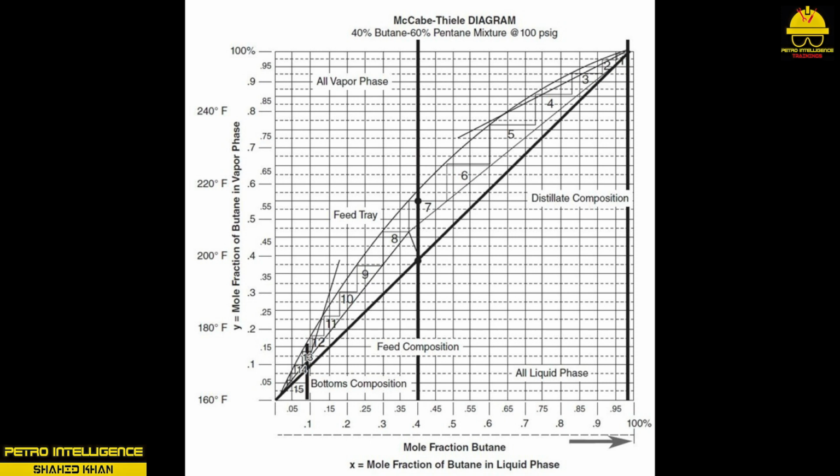Another important feature of McCabe-Thiele is the feed line where the binary mixture should be introduced. The condition of the feed is calculated by the slope of the feed line or q line. In determining overall column design, the McCabe-Thiele approach can help in identifying the required number of stages, degree of separation, and location of the feed tray. Other important factors include tray spacing, internal configuration, diameter, preheat, reboil, and cooling.